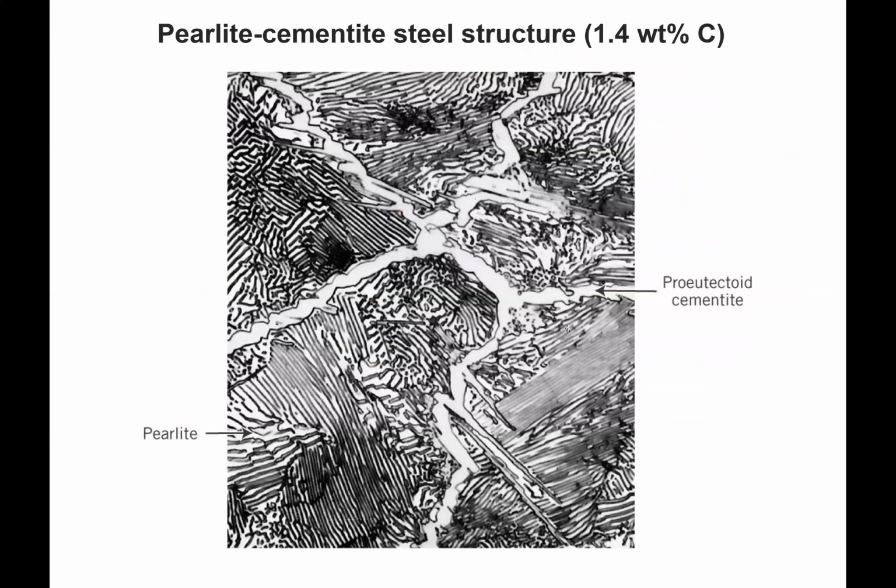So here's a micrograph of that. So now you can see this nice decorating of the boundaries here for the pro-eutectoid cementite. Notice in this micrograph, cementite is now the light rather than the ferrite. So this contrast isn't really due to the phases, it's due to the contrast that's set on the instrument. And so now everything is reversed. That's why you have to identify what your pro-eutectoid phase is first, and then you know what the light regions are in the pearlite then is, in this case, cementite in pearlite.